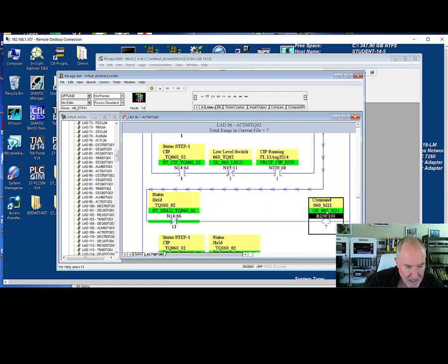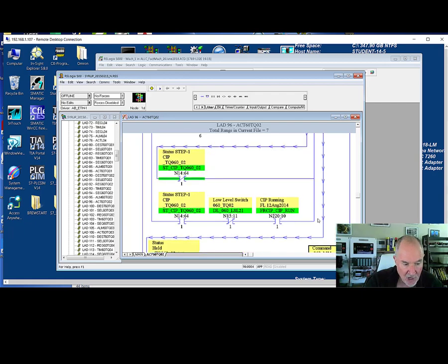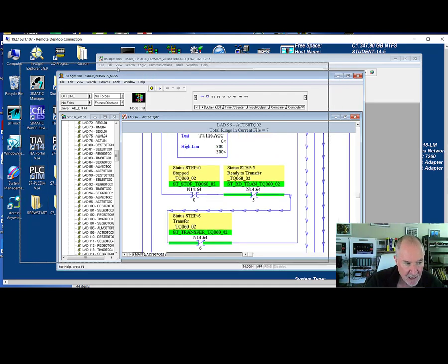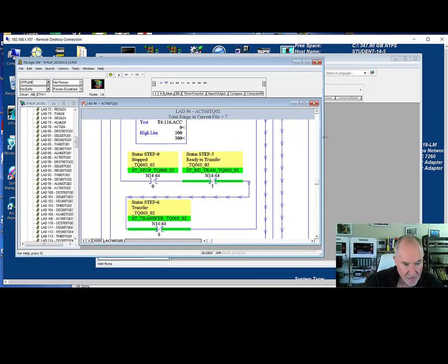So here is a command to turn on a motor. And this command goes into the DeviceNet routine and then is mapped as an output, right? So QB is a Q bit for M21, which happens to be a motor. So this motor will run if all of these things are true. And this is a pretty complex rung for ladder logic, but you have to deal with what's there.